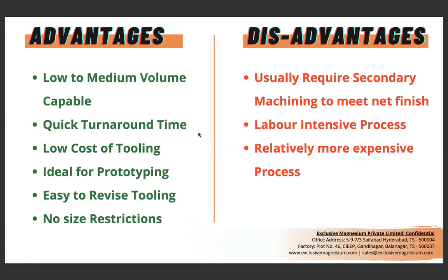It has low cost of tooling. Since it's done in wood or through aluminum, when it's a machined pattern, the cost of tooling is relatively low. The lowest tooling cost comes in sand casting, and this is only ideal for prototyping or for really small batches of production. I'll tell you probably the size, volumes, and all of that at a later stage.